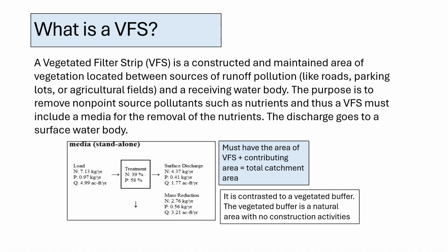The primary purpose of a VFS is to remove non-point source pollutants, particularly nutrients. Because of this treatment function, a VFS must include some form of media capable of actually removing those nutrients from the runoff. The treated discharge ultimately flows to a surface water body.